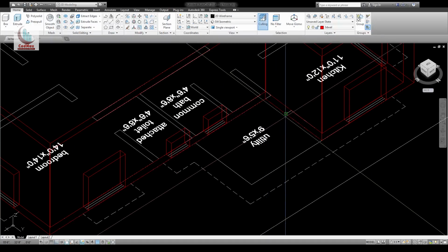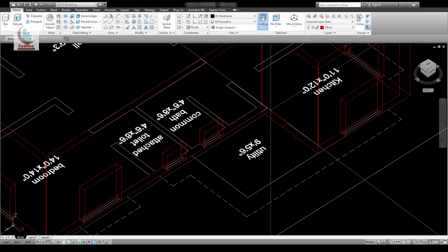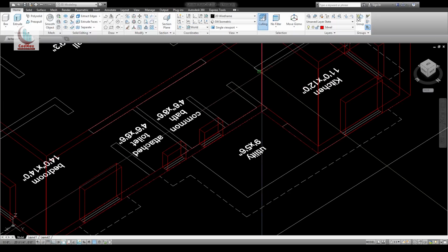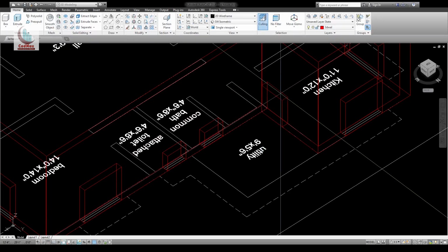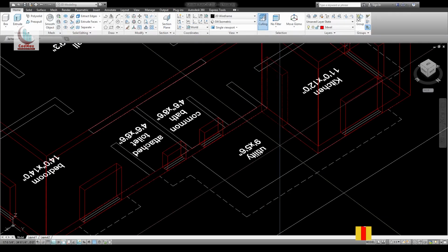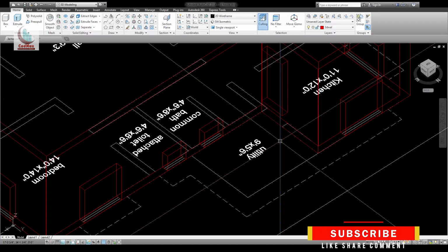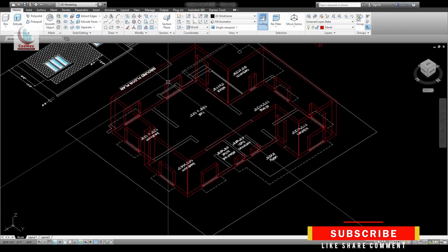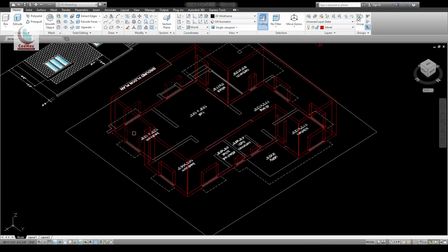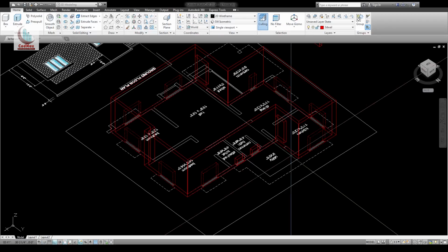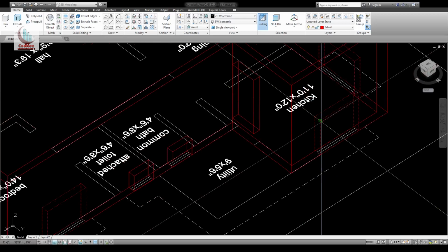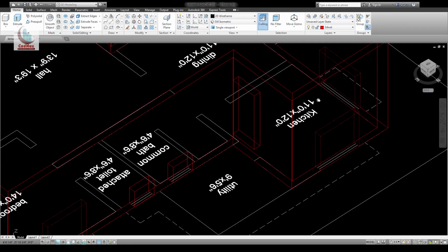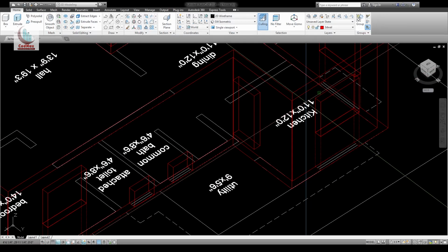Here there is a window, the door. Draw a rectangle, extrude that by 7 feet. Move the door by 1 feet 6 inch. Okay, zoom out. Now move all the windows up. Select the windows, only the windows, not the ventilator. Okay. Select this point and you have to move this in the Z direction.